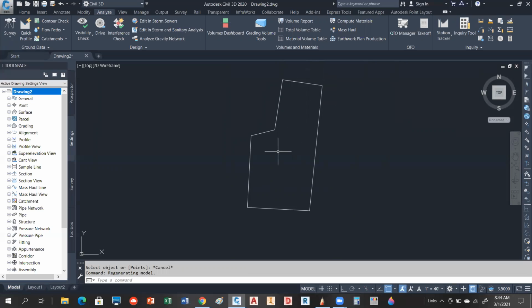So I'm going to generate a line coming off of this. Now, if you look at those bearings, you've got the bearing here and the bearing of the roadway. If you add those together, you'll see that that's a 90-degree kind of thing. So especially with subdivisions, a lot of times lines are going to be either parallel to something, or they're going to be perpendicular to something, or they're going to be radial to something if you have a curve.